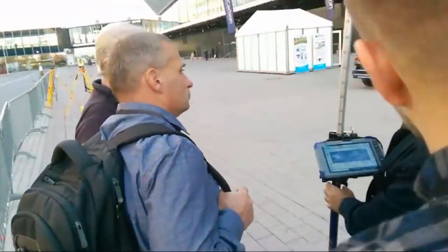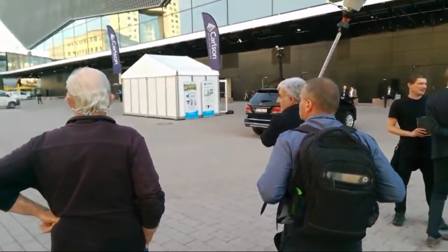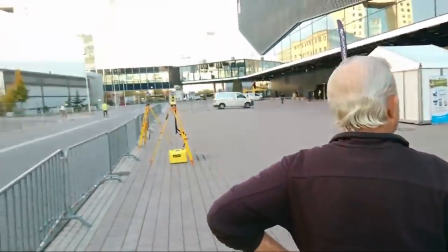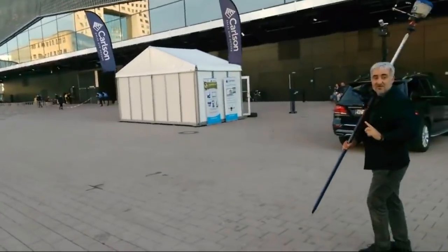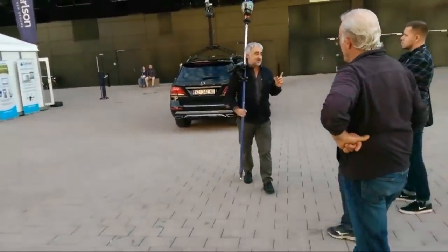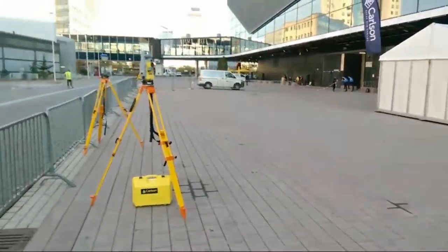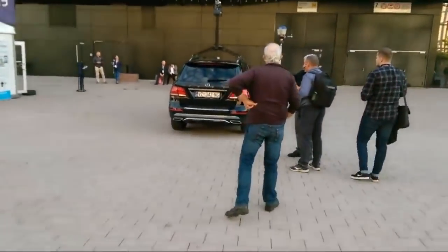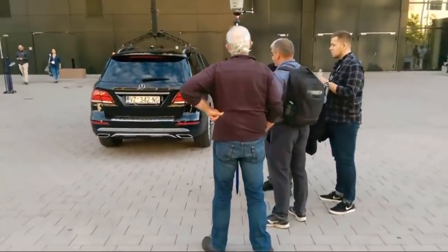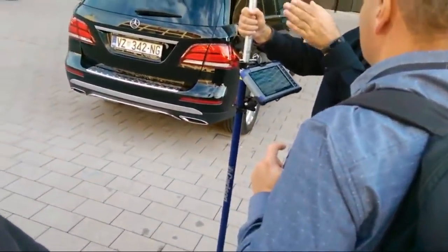So the first thing to show is if I move now, I'm not locked. But look at this. This is the follow me feature. Every 3 seconds it goes to my position. That means it's not trying to lock the prism because Survey Pro knows I'm walking. No way to search for the prism, but when I stop, look at this. Then it knows I'm standing by, it's been close, and it wants to measure now. So I search the prism, lock the prism, and let it measure with the total station. That is what it wants to do.